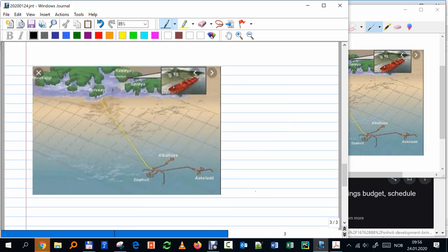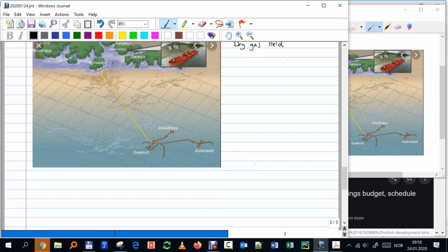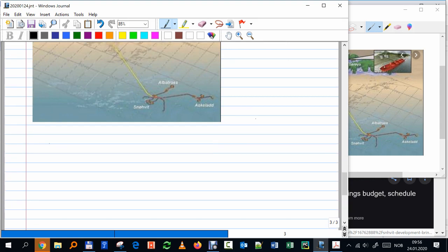One of the things we can say is that it's a relatively dry gas field. If we sketch its structure, the way it was originally, it was three wells producing to a common point. These wells are in what we call a template, a subsea template, from where I drill all of them from more or less the same point, and then they are deviated into the formation.